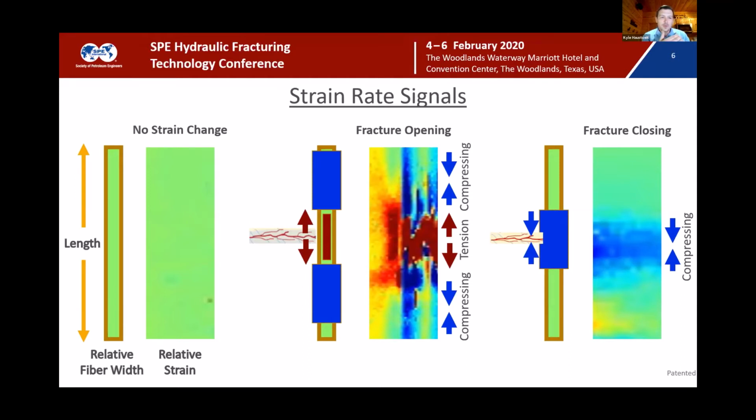So the speed at which the light pulse comes back to the surface is the speed of light divided by 2. That's why we're able to get tens of thousands of measurements per second. And the entire cable is the sensor. That's what's unique about fiber optics, is the entire cable from surface to downhole is the sensor. And as we interrogate that and things change in the cable, the way the light backscatters also changes.